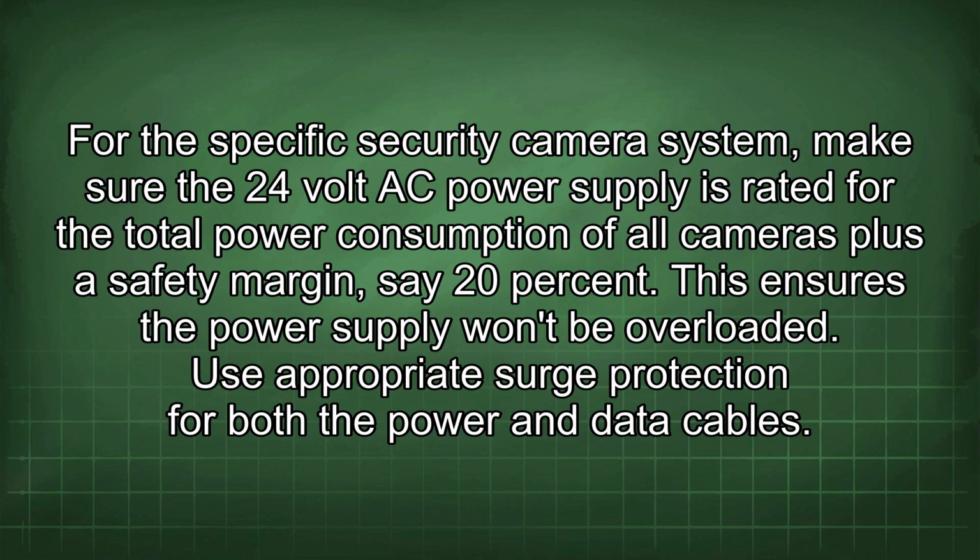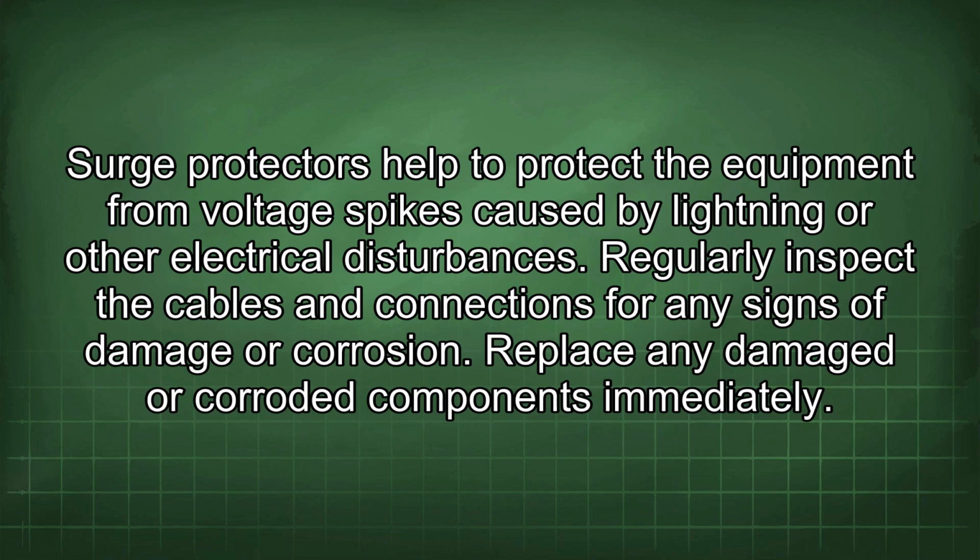Use appropriate surge protection for both the power and data cables. Surge protectors help to protect the equipment from voltage spikes caused by lightning or other electrical disturbances. Regularly inspect the cables and connections for any signs of damage or corrosion. Replace any damaged or corroded components immediately.